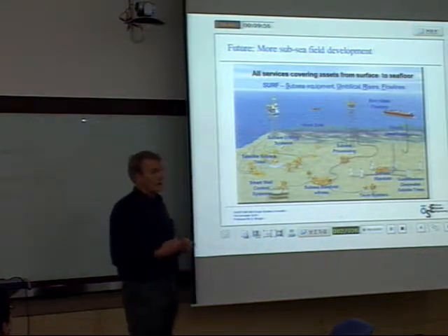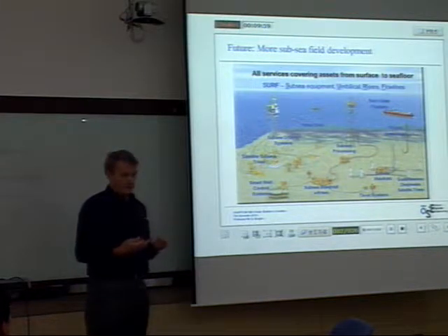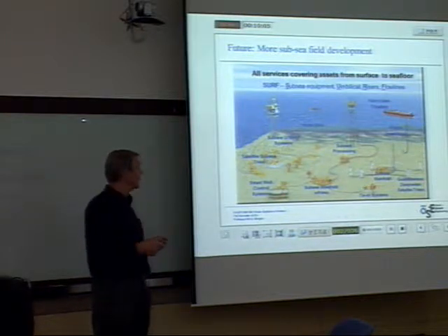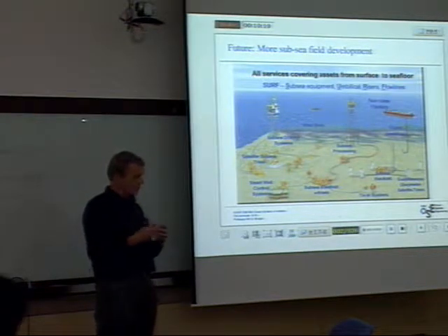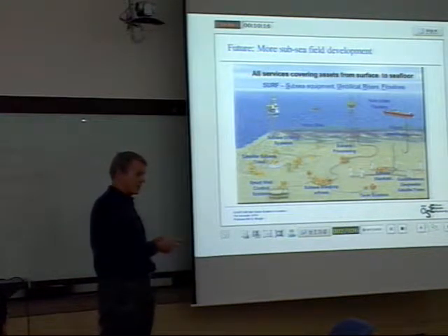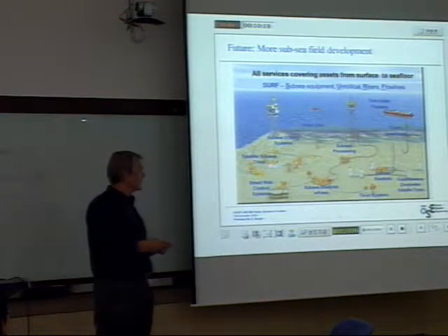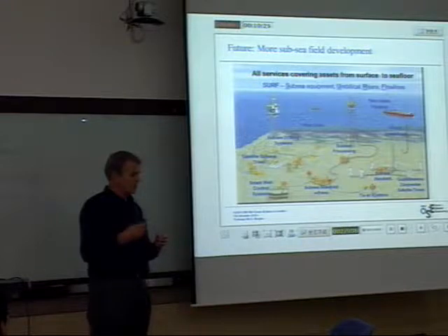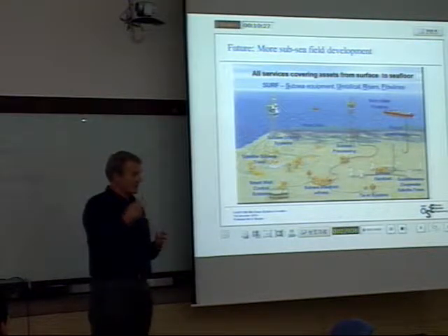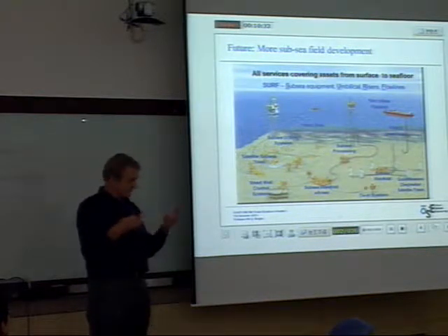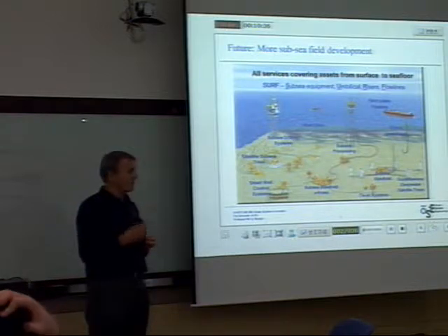Typically, you'll have something where you have two fluids or even three fluids at the same time in the pipeline, because here you have not processed, right? If you have processing, then of course you can do some separation, let's say sending the oil in one pipeline and the gas in another. But nowadays one has technology for two-phase flow, that is both a gas and a fluid, oil mixed with water in the same pipeline. So that's advanced technology.